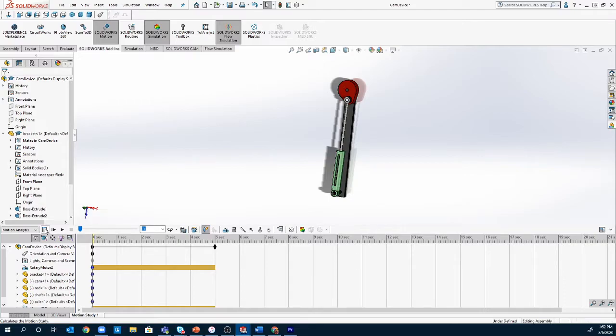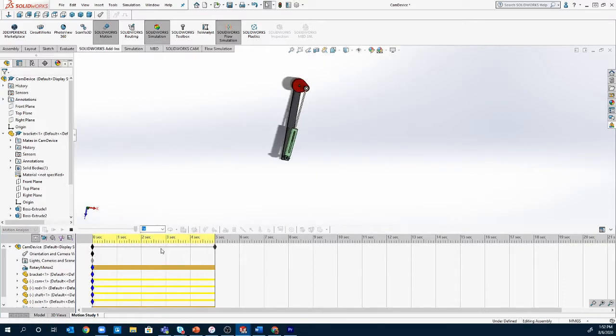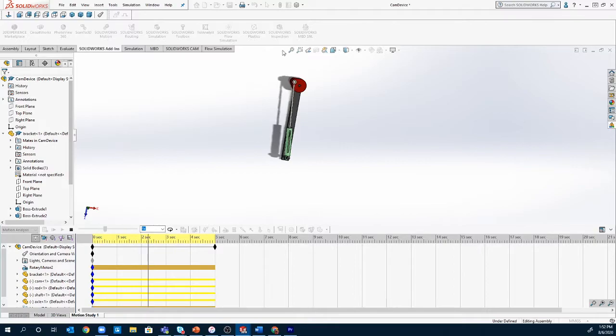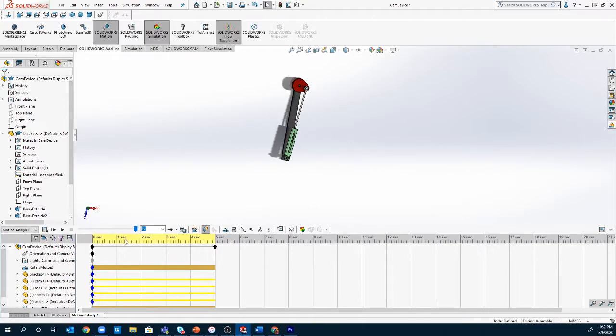So let's hit that button, and you'll notice that the thing starts turning. In this case, it only turned around 2 times, and if we run it again, you can see that it slowly turns around, and that's due to the speed that it's running at. Right now, it's in a jog mode because you can see that this here has a loop around. We can pull down that menu and go to playback mode normal, which will just play through once and then end. The sound there is telling you that you're at the end of your animation.